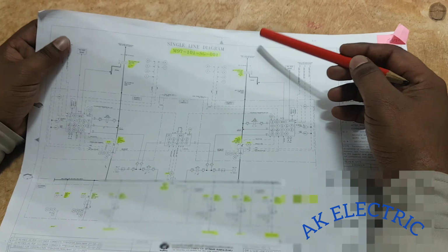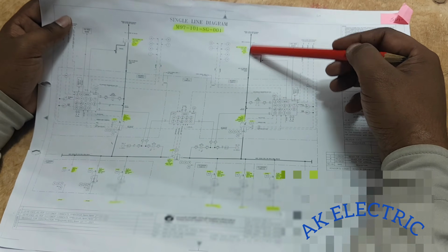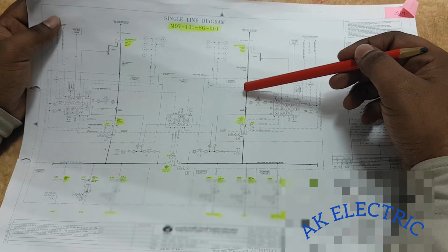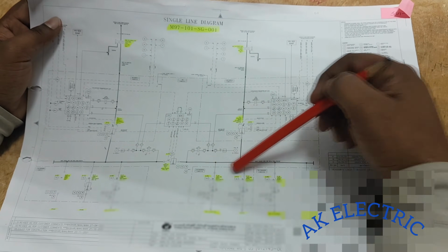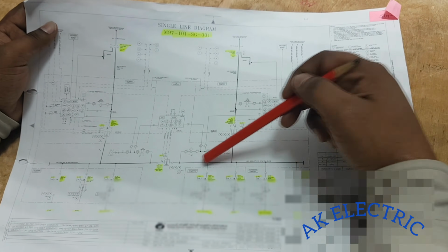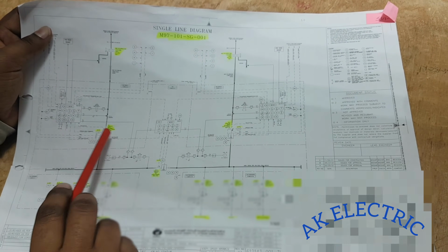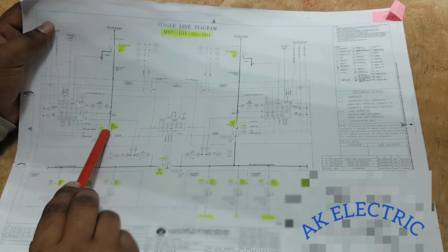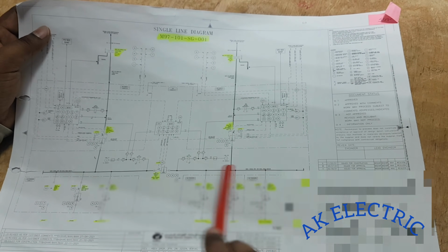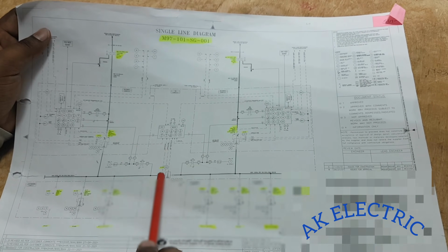Okay, same like this, transformer voltage 480 volt will come here. Once we switch on the breaker, supply from line will go to bus and energize it. Once we switch on the breaker, supply will energize the bus B. Now we switch on incomer 1 breaker as well as incomer 2 breaker. So bus A is energized and bus B is also energized. This tie will remain open.